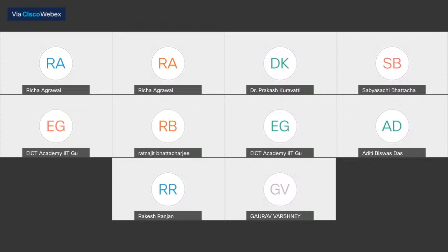So for a practical antenna, if we say that the cross polar separation or cross polarization is better than 30 dB, we mean that this Y component, even if it is received, will be 1,000 times smaller than the desired one. So in that way, you can define the cross polarization. Do I answer your question?